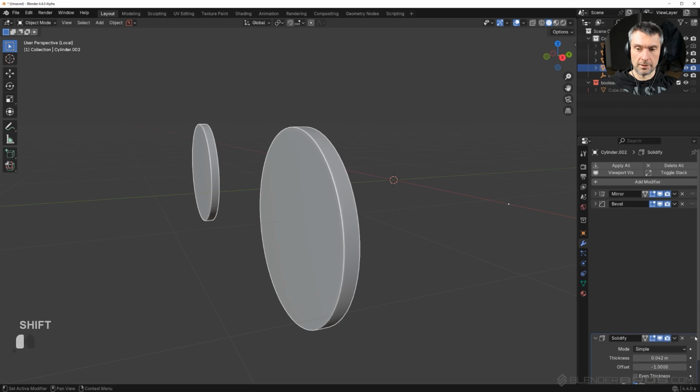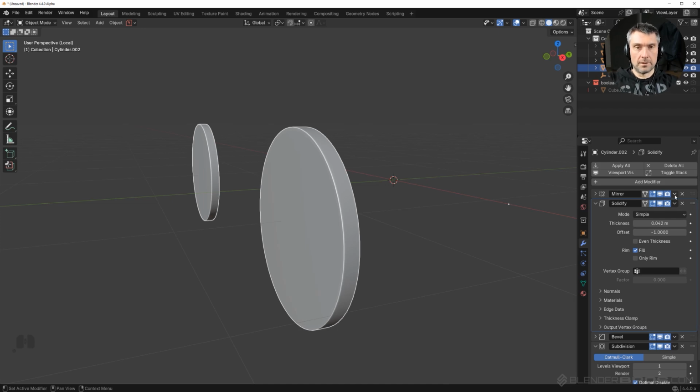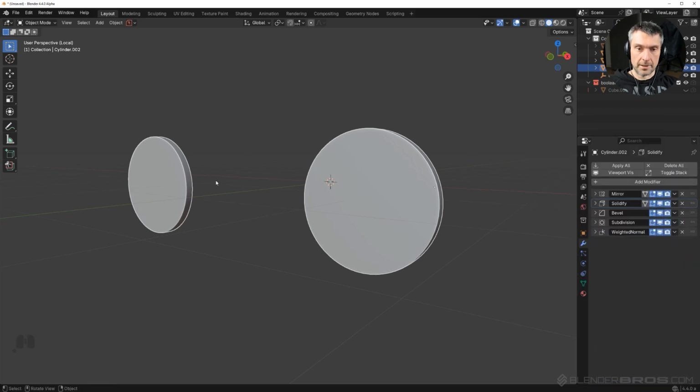Look at this, right? If I move it in here, disaster. Why? Because bevel is not holding the solidification. The model is being solidified, then bevel is holding the edges, and then subdivision is making it smooth. Do you see what I mean? So you need all that in order. It's really important, okay? So let's toggle this, and we're good to go.